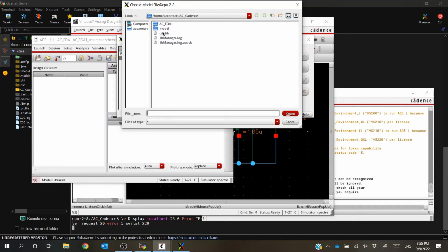Right now, this is, again, my Cadence folder. And if you remember that model folder that we copied over from Dr. Lee previously, we can double-click Model, and this will give us all of these different types of model files. So we can see that there is an N type and a P type. And if you are thinking ahead, you might say, that's cool, there's an NMOS and a PMOS. And that's exactly what this is for. So this is going to be accounting for NMOS, all these different N's here, and the PMOS.